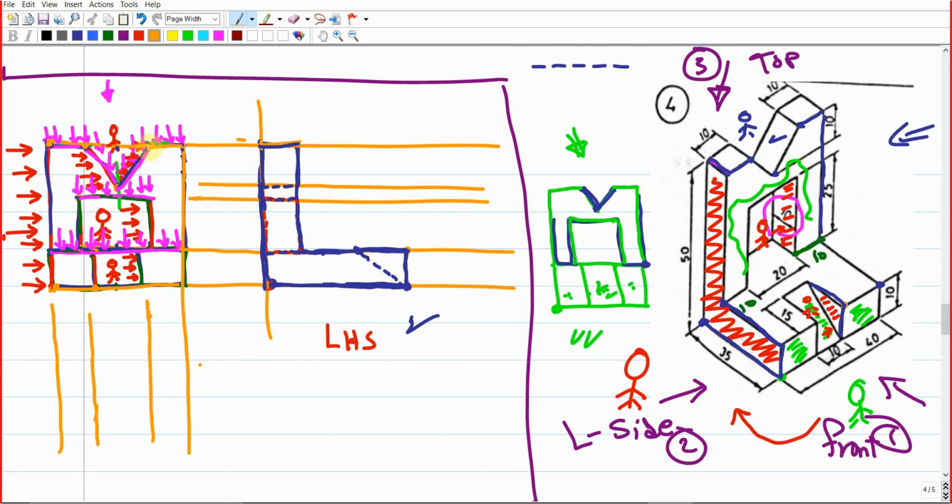Make sense? Also, there is a line in the middle because of this inclined surface. From the start point, I draw a line. From the end point, I'm gonna draw another line in the middle here. If you see this horizontal line, and from the start point I drop down, by chance we get that this point is identical to this one. And this point is considered to this line. And this horizontal line from start point, end point, so these are the lines that we can project from the